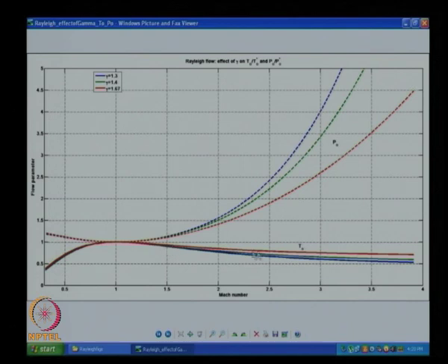Okay. I was finding that when the gas is more compressible, it can handle a little more heating. Okay. So, it will not reach choking as early as the less compressible gas. It can get a little more compressed and try to squeeze through the gap available. That is the way to think about it. If it can squeeze through, that means it is more compressible, right. I just want you to get this physical feel so that you will never forget this. That is why I talk about squeezing through the same area and stuff.